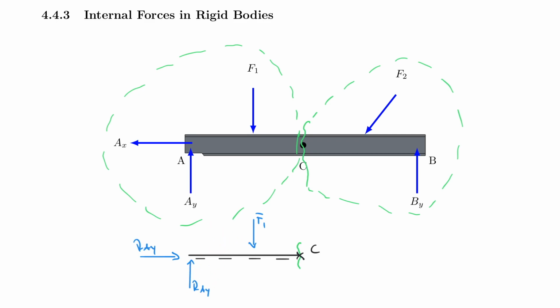So what you have to do is you have to bring in your internal forces, which now, by the way, are external forces, right? So by me cutting the system here, and sometimes I give this a name, like I call this here cut 1, and I call this here cut 2. And of course, here I have given cut 1. And because I have extracted cut 1, the glue here is now out of balance, and I have to put that back into balance.